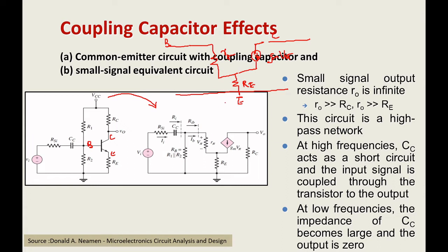Now other than that, you can see here I am removing the VCC. So R1 and R2 will come in parallel. So R1 is coming parallel to R2. Then the capacitance I am considering because I want to study the cutoff frequency formula and other parameters. Then the signal resistance will be in series, RSI, and here you have an input AC small signal VA. So this is about the left side. On the right side you can see I am removing the VCC, so RC will come to the ground. And here is the output, right?